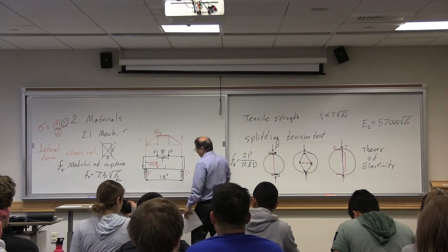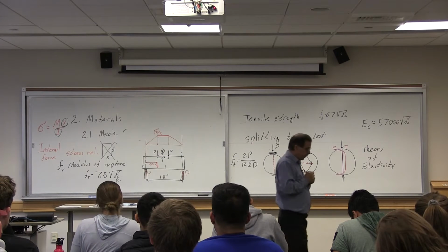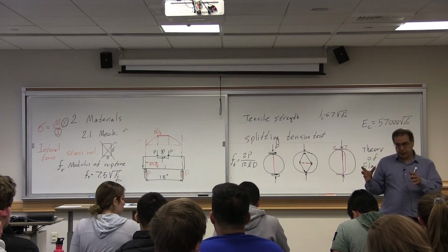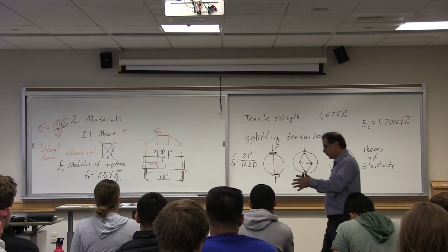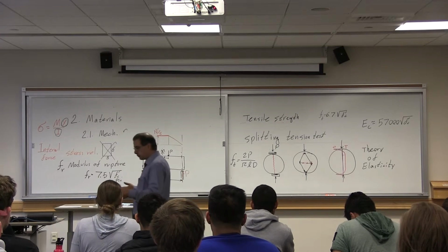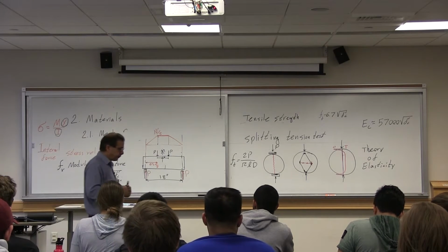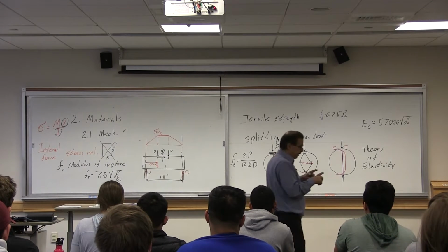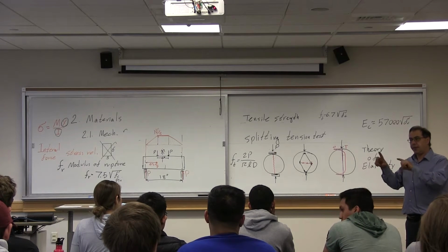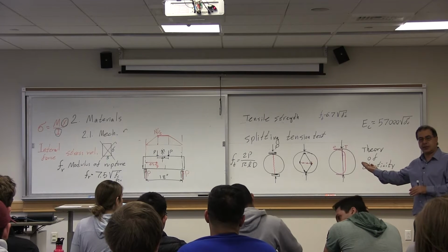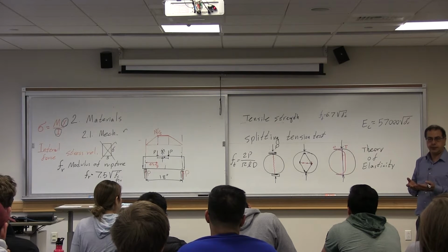Okay. So let me maybe bring up some bigger picture type of thing. You make samples of concrete, either cylindrical or cubic, and go to the lab and test them. What you find is the stress-strain relationship. You then use the knowledge of statics to find internal forces. Then you relate the lab test results and the knowledge of statics through solid mechanics to do design.